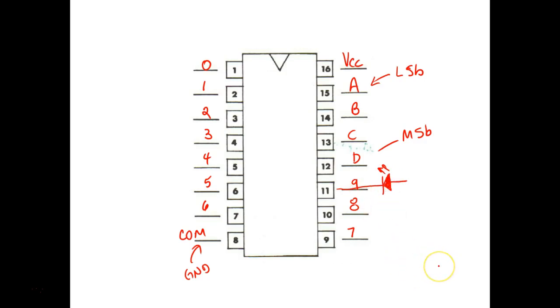Of course, the way the light emitting diode works, and we explained this in class, it drops around 2 volts, and we like to get about 10 milliamps through it, no more than 15. So if this goes low and I connect this to plus 5 volts, it's either going to blow the output of my 7442 or it's going to blow the LED.